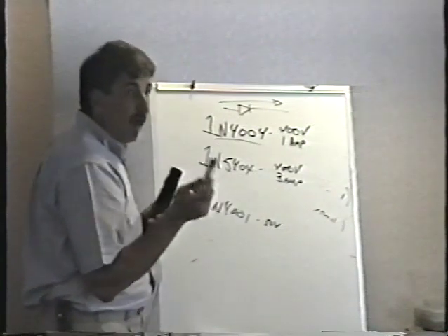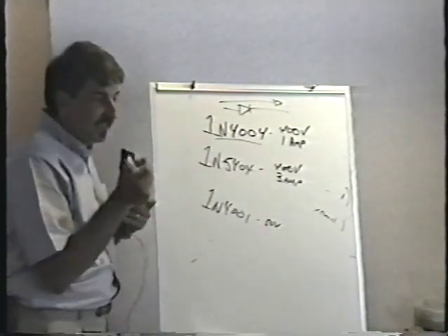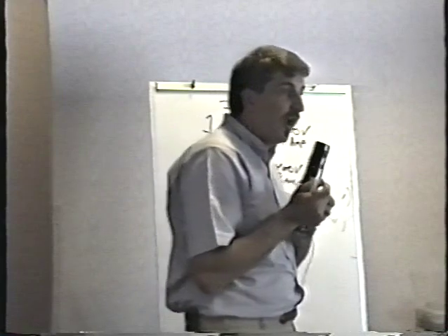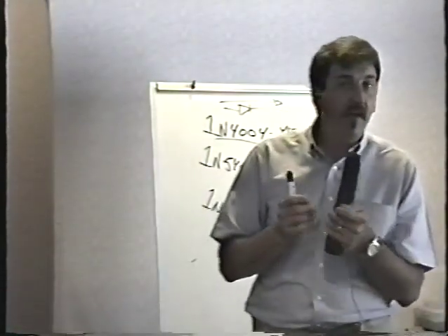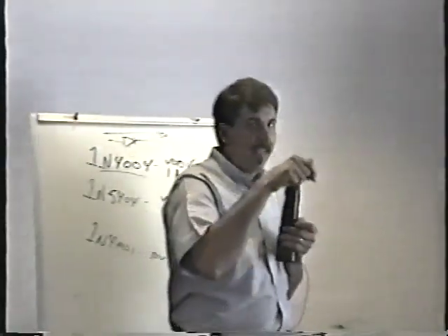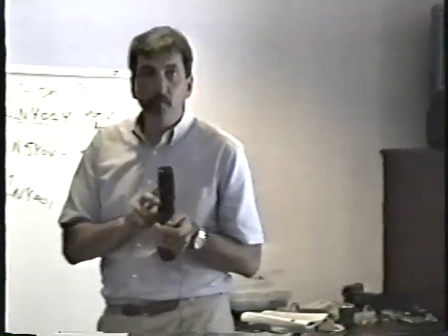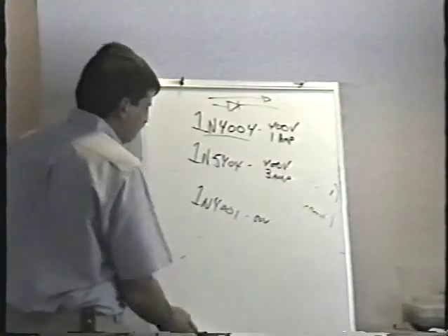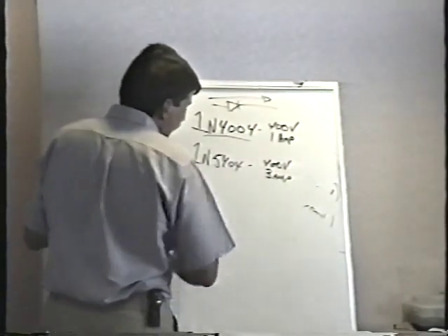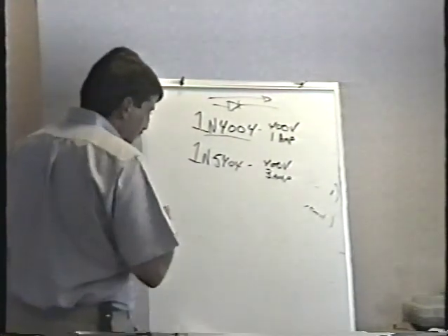Absolutely. Only problem, look at the size of the leads. You see how fat the wire leads are on the 3 amp diode, the 1N5404. The component leads are very, very fat, and you may not be able to get them in the hole. Rather than make a big hole in the board, if you ever have to do this, and I seriously doubt you will, here's what I do.